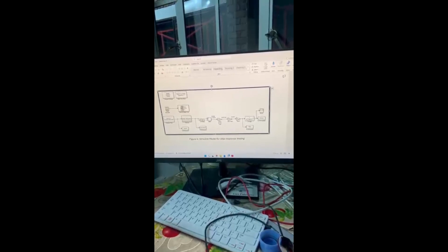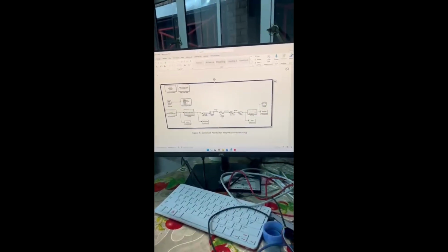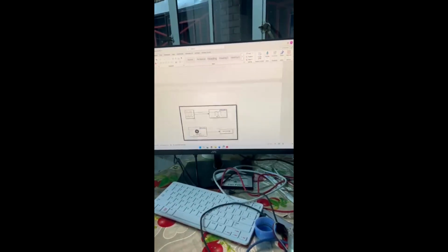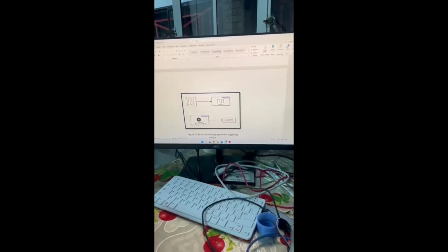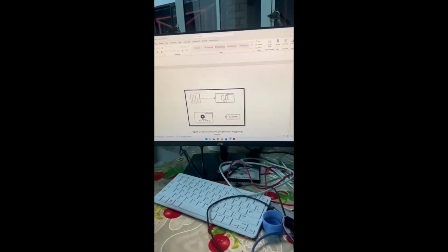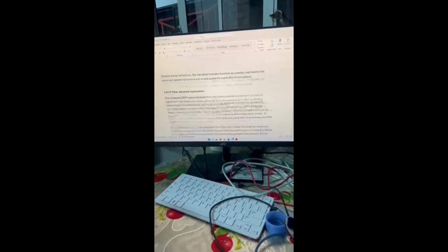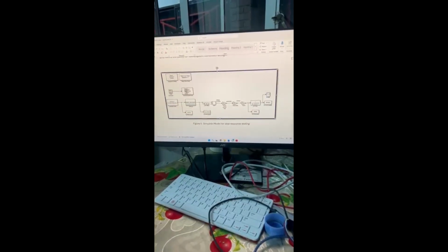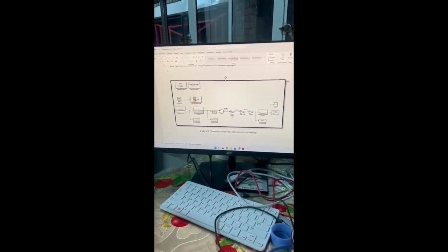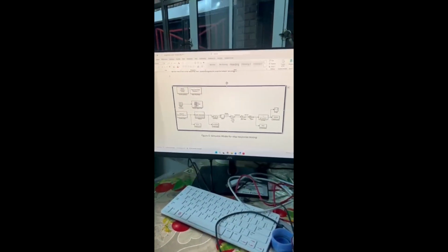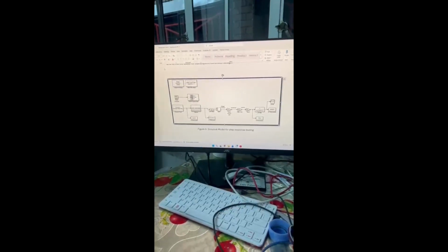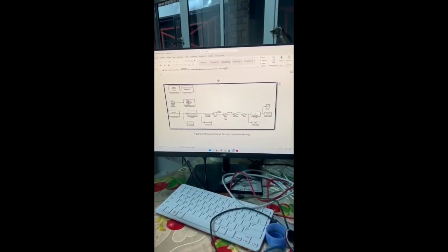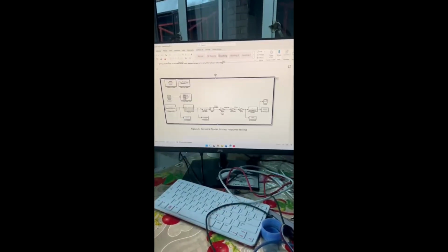So this is my Simulink model for the step response. Initially, I started off with a simpler model, this one, simply to test the triggering of the motor, and it was successful. Then I moved on to the more advanced model, which is this one. So the way this module works is basically it's a Simulink program that implements a real-time motor speed measurement control using the Arduino encoder block interface that's available on MATLAB.